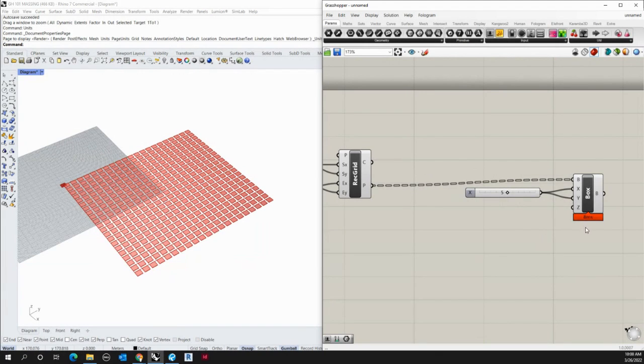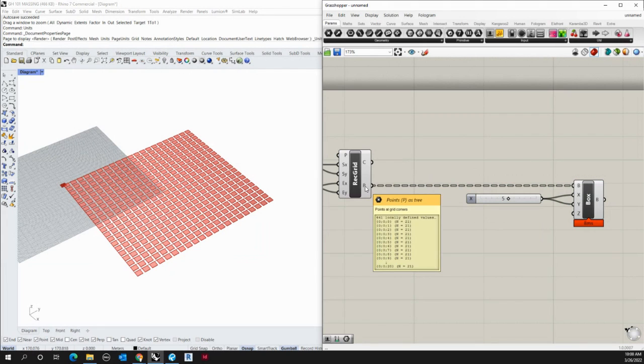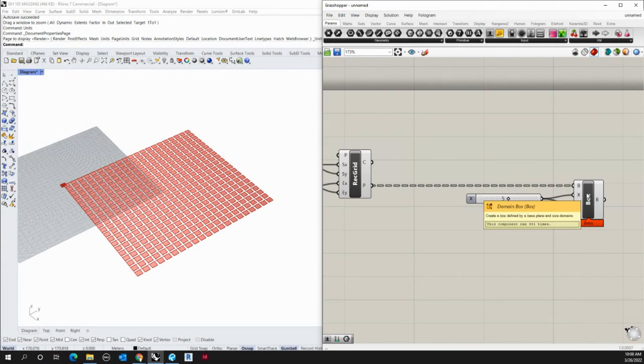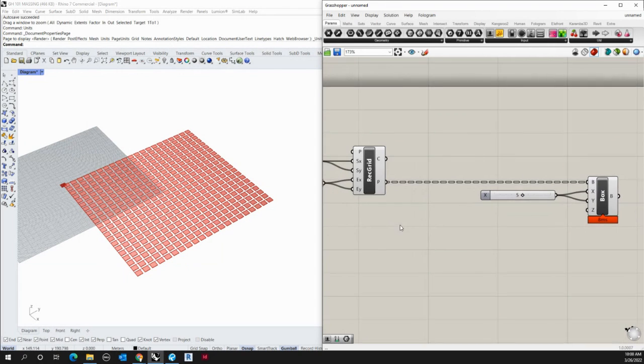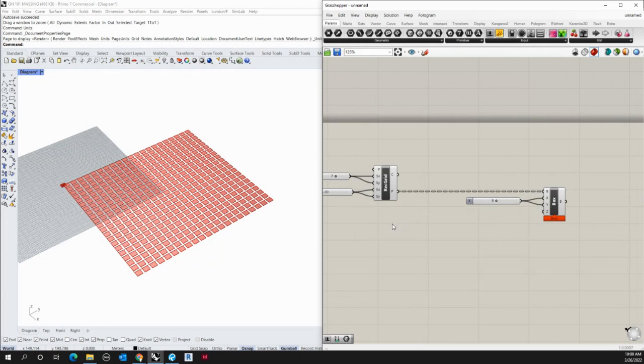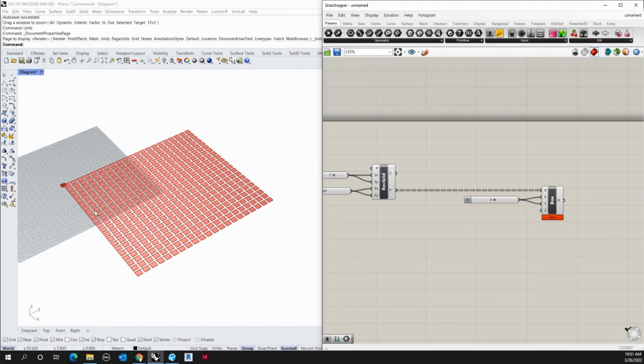But with the point itself, you can see as I'm putting a list of points, and we'll go through the list after, I'm putting a series of points into the box component. It's creating a box at every single point that the grid generated. And that was also a question earlier about the sphere. How do I do multiple spheres at different point locations? Well, you simply have to input in the center, the reference of your sphere, a lot of points in there and you'll create a sphere for each point.